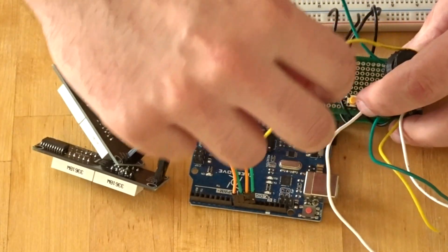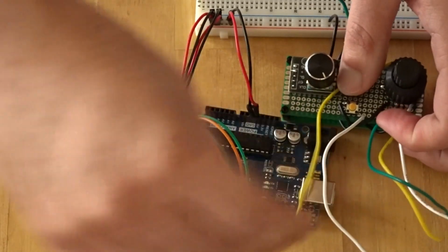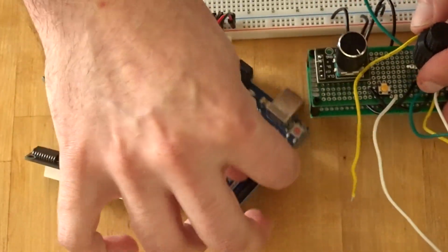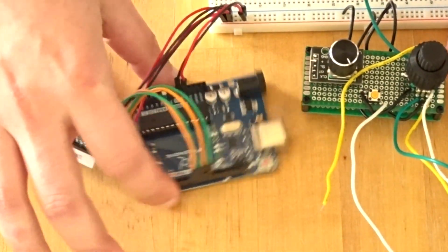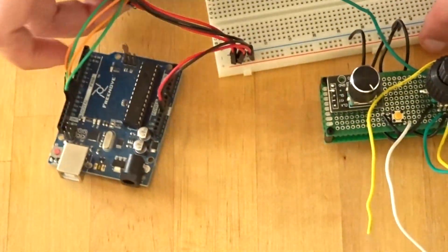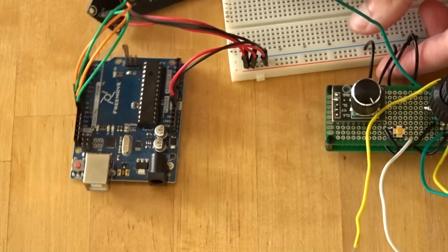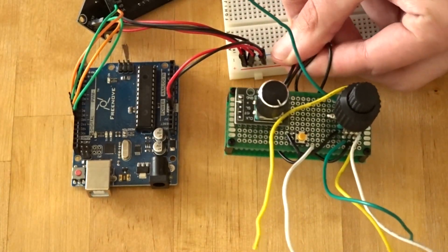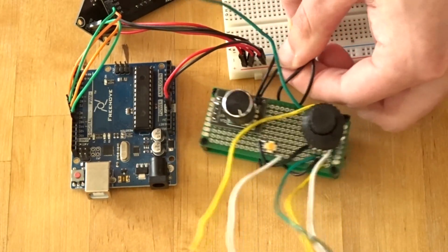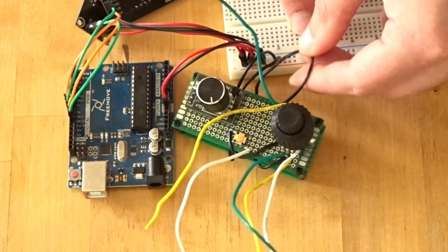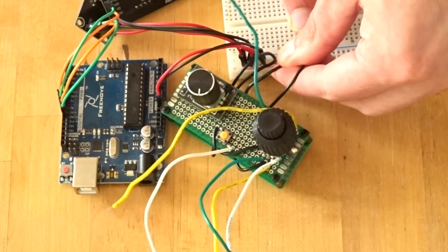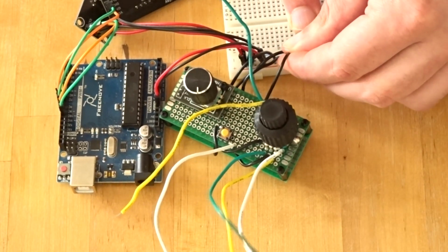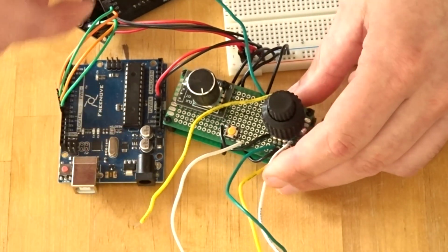Now, when I'm going to code this up, I'm going over this in full detail, but the yellow and green wire are the A and B pin of our encoder. And we need to make sure that either the A or the B pin is connected to pin 2 and the other one to pin 4, 5, 6, 7, doesn't matter. But as long as one of the 2 pins is connected to 2 and from the other encoder to 3, we make sure that we use the interrupt pins available on our Uno.